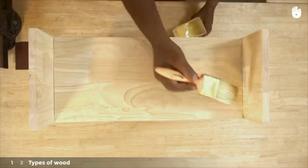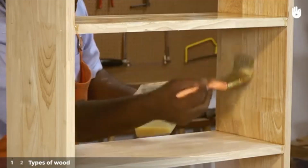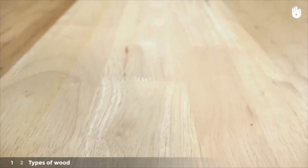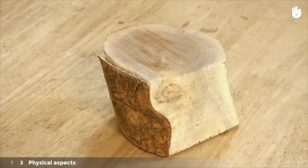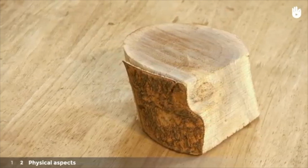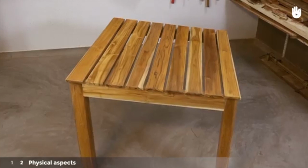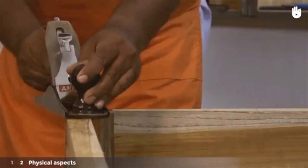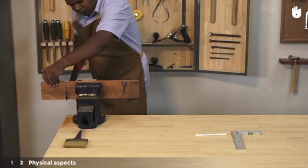Rubber wood is extremely vulnerable to warp and rot, and needs to be treated with preservatives and laminated to improve its durability. Boards of rubber wood are made with edge-glued or finger-jointed pieces. Physical aspects. A solid wood workpiece generally has grain patterns resulting from the arrangement of wood fibers. The most basic pattern is the straight grain that runs parallel to the longitudinal axis of the workpiece. Generally, when you cut or plane a workpiece, make sure that you do it along the grain. When you cut a piece of wood across the grain, you have an end grain on the side.